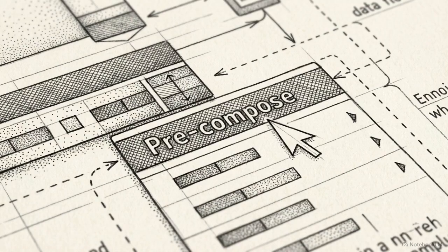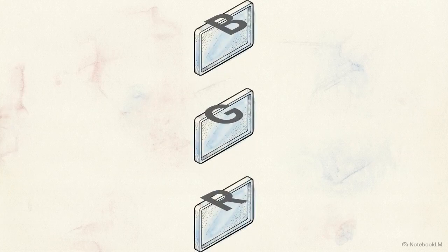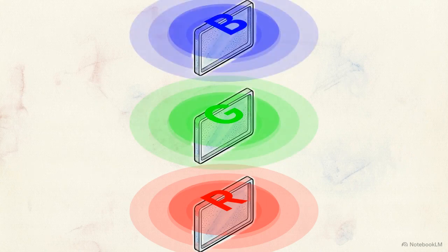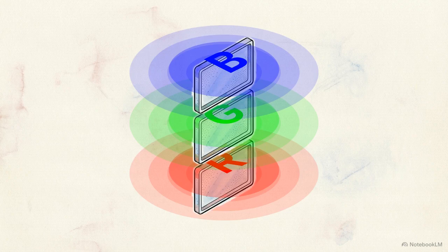To build a proper RGB glitch, start by pre-composing your text layer. Then duplicate that pre-comp twice so you have 3 identical layers stacked in your timeline. Next, apply the Shift Channels effect. Set the bottom layer to display red, the middle to green, and the top to blue. At this stage, the channels block each other out, showing overlapping primary colors.